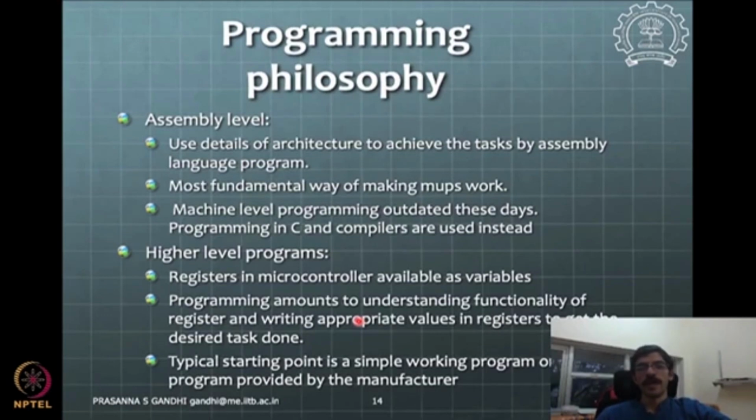Then there is yet another level of programming where you are heavily dependent upon libraries. There are commands in the libraries that carry out the operation you want to do, and you have to supply those functions appropriate data as arguments. TIVA based or ARM Cortex based microcontrollers will be programmed in that kind of way. We'll get into more details about that as we go along, but for now maybe we'll stop here.